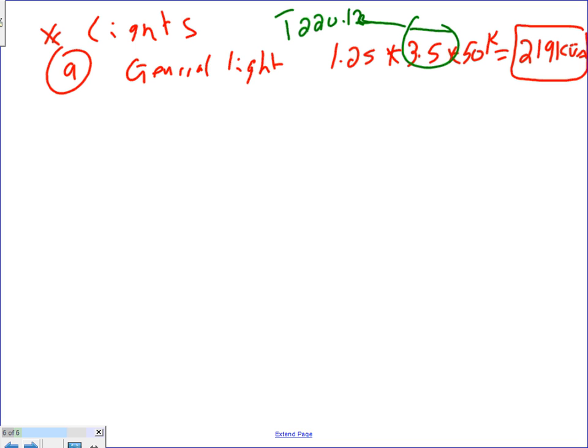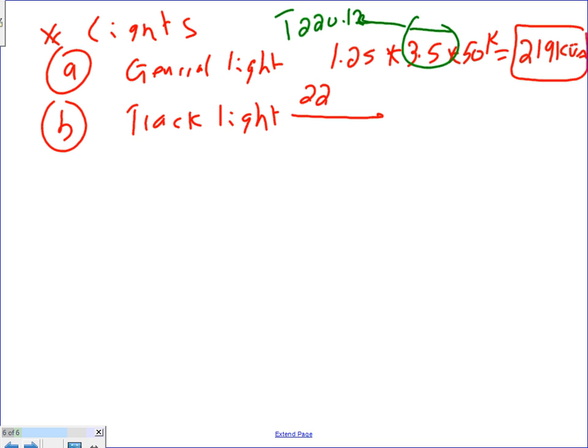Okay. That's A. B, track lights. Let's do the track lights. I have 220.43(B). I hope somebody will verify that one for me. If you go there, it says for every 2 feet, multiply by 150. So, piece of cake. 1.25 because it's a continuous load.